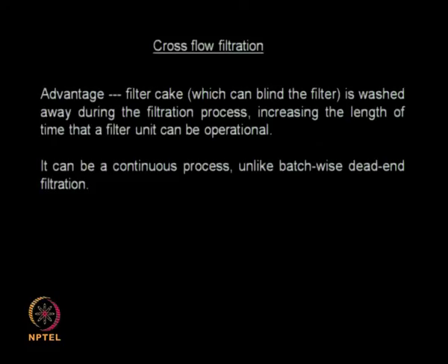In a normal dead end filtration, after some time you need to remove the solids, that means it is a batch process, whereas in crossflow filtration we can do it as a continuous process. So that way I can prolong the filtration time. That is the main advantage of crossflow filtration.